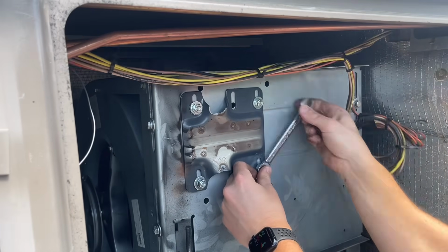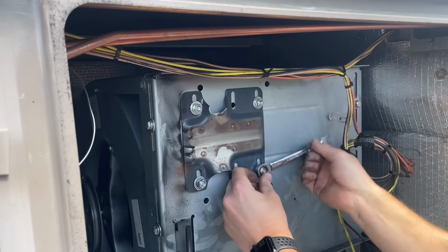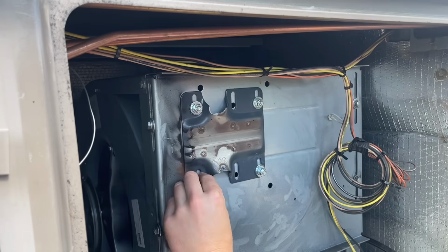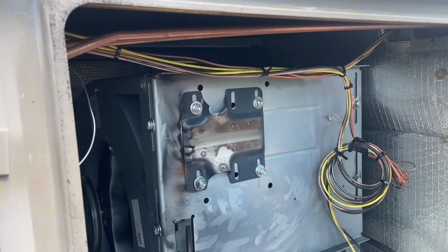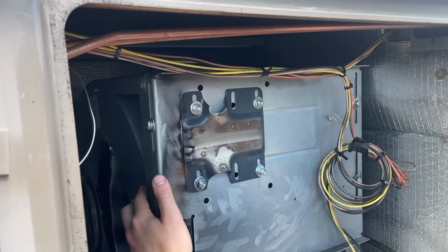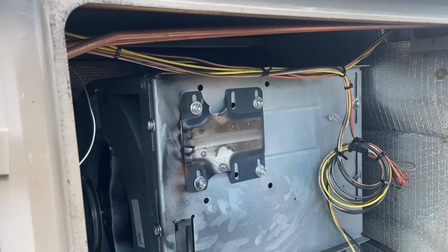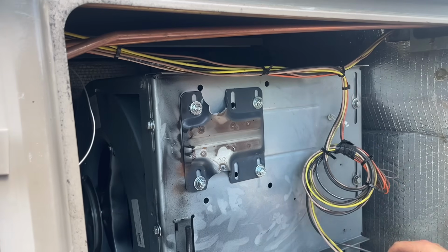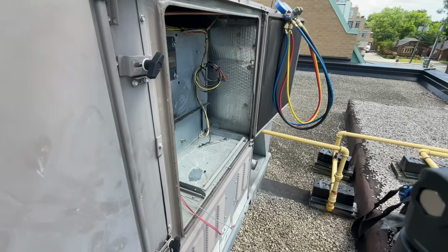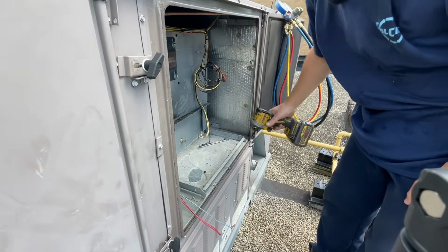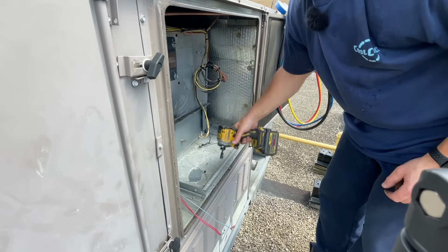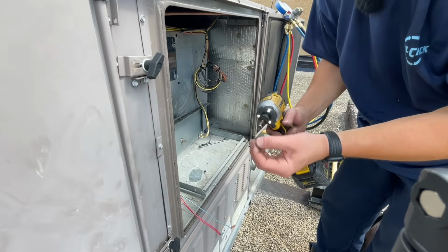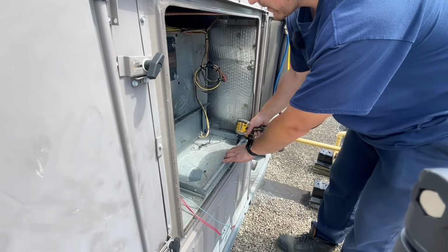Now let's take off our old defective bracket. And of course, some manufacturers will put a spot weld on the back of the bolt. Of course, York didn't do it for us, so we're gonna have to gain access to this a little bit better. I'm gonna show you guys how to pull out the slide on these. With this particular model of rooftop here made by York, they have a couple 5/16 screws here, and of course this one's stripped.